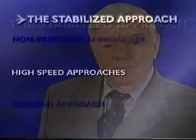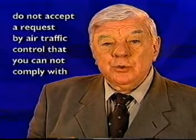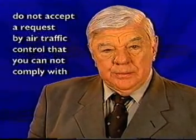High-speed approaches. Those pilots who are used to flying into busy hubs know it too well. ATC often requests to maintain an above-normal airspeed during the arrival phase of the approach. To prevent non-stabilized approaches from happening, here is a set of recommendations. Stick to your limits. Do not accept a request by air traffic control that you cannot comply with.